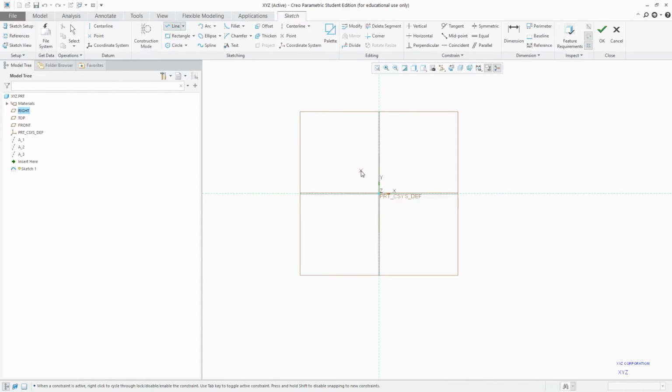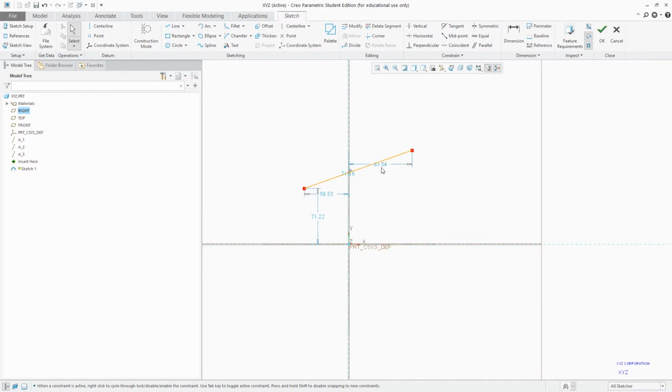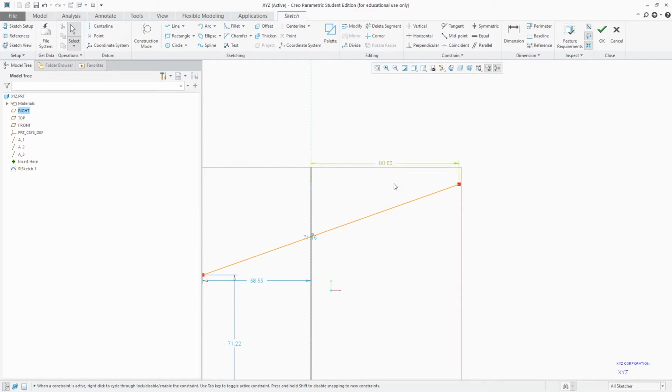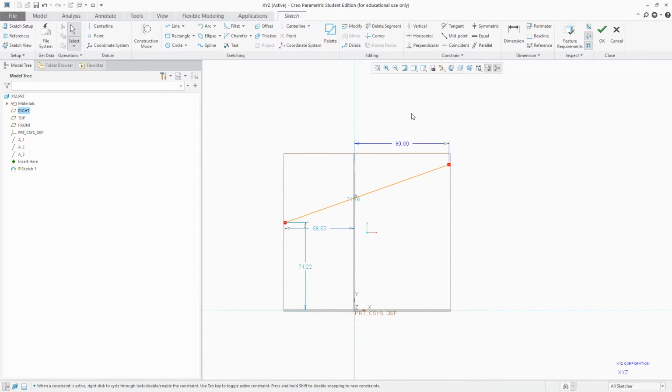Now I guess I have changed the value, so this time this will turn royal blue from sky blue instead of turning red. I hope so. And now you can see my dimension turned blue. Blue specifies like I have changed the value, and this is strong dimension, and you can see here by hovering my mouse cursor on it, the dimension is strong compared to these ones.